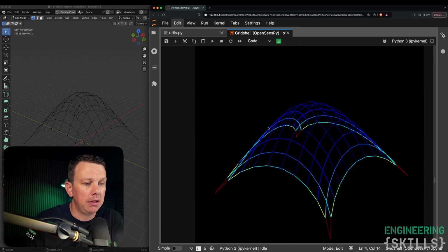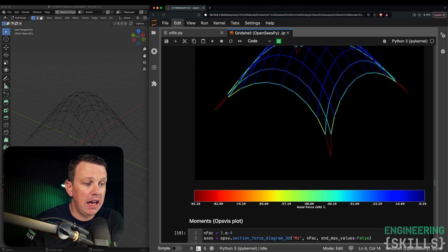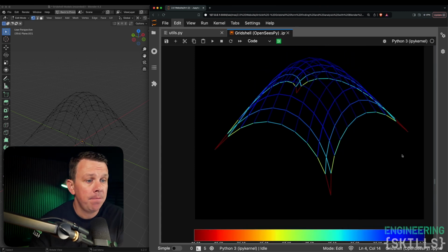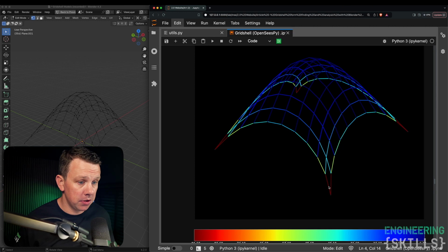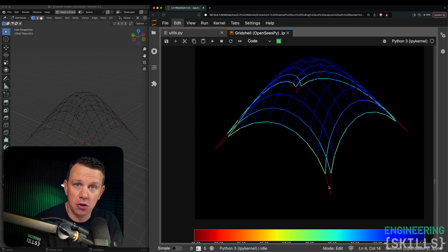One nice thing we can do is, if we just see the structure first, this is our structure with the axial force distribution, and of course we have our range of forces, noting again that they're all compression forces, all the numbers are negative, and so the whole thing is in compression, which is exactly what we would expect. If we look at the actual force distribution itself, naturally enough we see the largest magnitude axial forces down in the members adjacent to the supports, because if we think about it, all of the force is being funneled down the load path towards the foundations, and it's those members that are taking all of the forces down into the foundations. So the intensity of axial force is increasing as the number of members that force is distributed across is reducing.